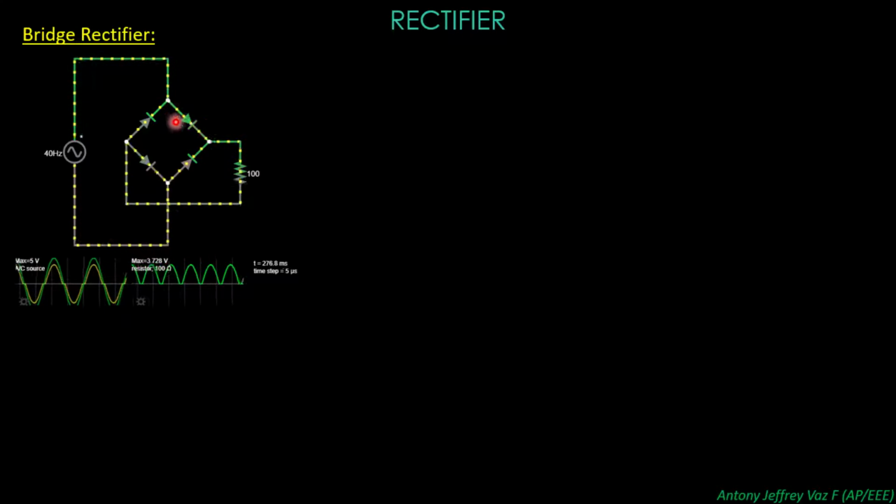In this case, the positive biased voltage is present only at this diode, because when the positive end is coming here, only this diode will be in forward biased condition. This diode is in reverse biased condition because the sine wave is at the positive peak.